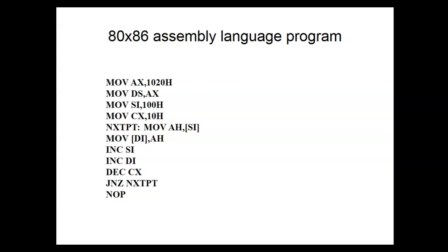So this is assembly language. You still have to know a lot. AX is one of the registers in the processor. I'm going to take AX and put it in that address right there, which is a hex address. But now it makes it a little easier, right? Because I'm not dealing with all these operational codes. But I still have to know everything about the processor. This is called assembly language. We have a program called instruction list that's almost identical to this. So it married with assembly language.